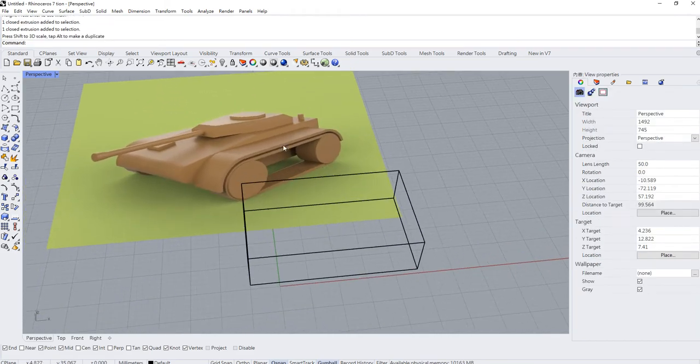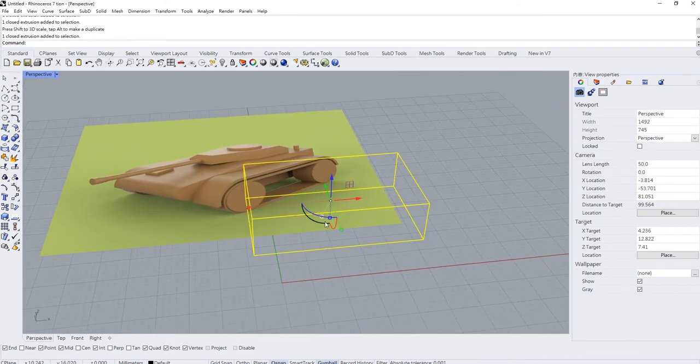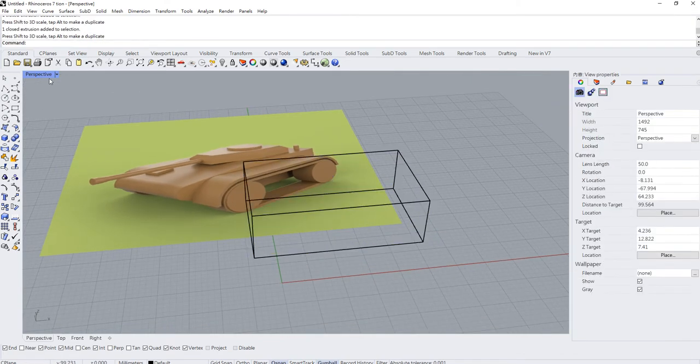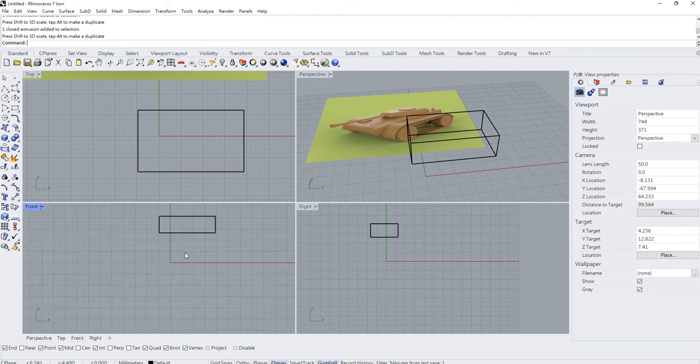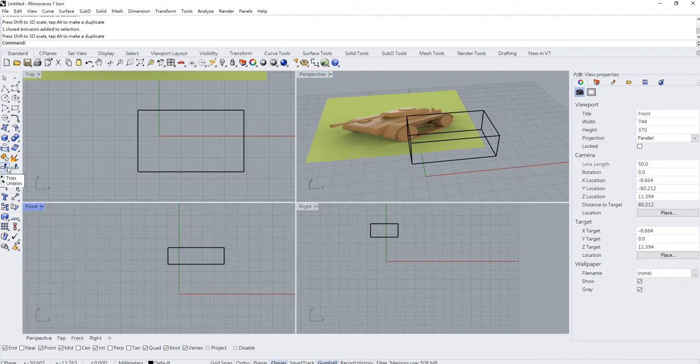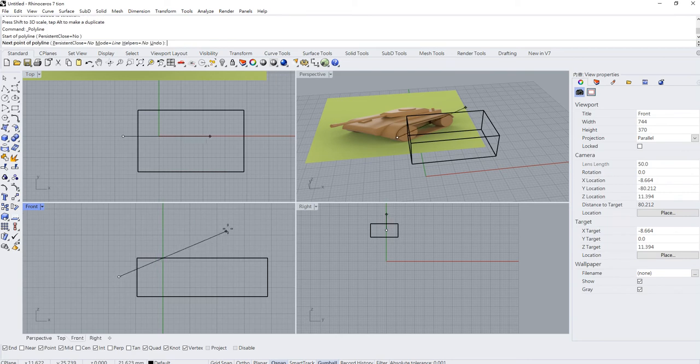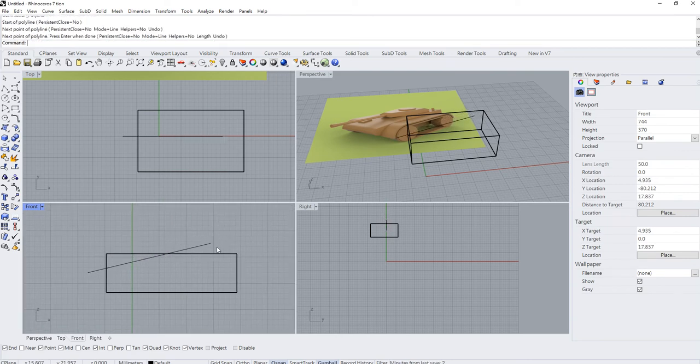Okay. And then let's cut off these geometries. Let's cut off this area. I will scale up a little bit, and then go to the side view. If you remember, we can use split or trim or boolean split to do that. So let's use curve, and I will cut in these directions. Create a curve. You want to use that one for cutting, and this part as well.